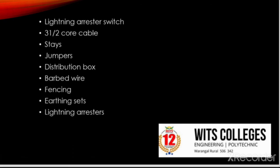The next one will be jumpers. These are used to connect 11 kV lines. Generally we use ACSR conductor, that is aluminum conductor steel reinforced, for the jumper purpose. Then fencing. It is provided around the poles or plinth to prevent the entry of animals as well as children.